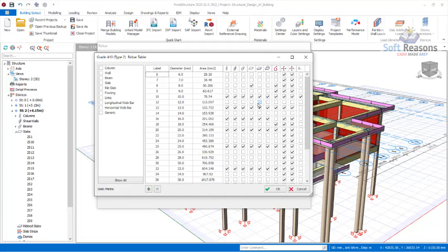For instance, the first column right there is the reinforced concrete column, and you see the rebar selected is 10, a 10 millimeter diameter. We wouldn't want to use this rebar diameter in this structure, nor 13. We need 16 as our minimum rebar diameter, then 20, 25.